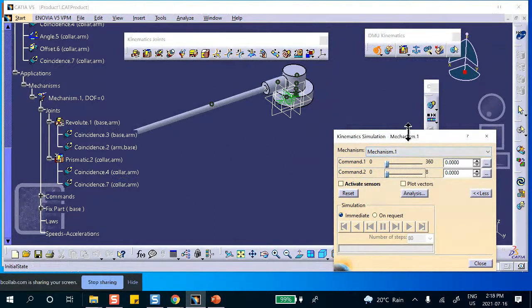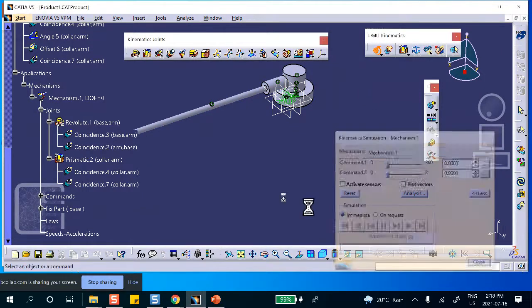It's just like you driving a car. The steering wheel and the gas pedal, they're under your control, but there are 2 degrees of freedom, independent degrees of freedom. Okay? So now what we're saying, we're going to say, okay, we're going to tie these things to time by saying that this has a speed of 1 inch per second, and this rotation has a speed of 1 cycle per second or 60 RPM. So this is fine. There's nothing wrong with it.